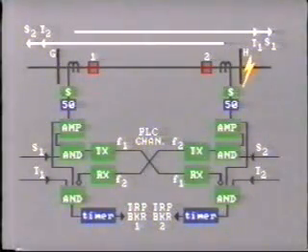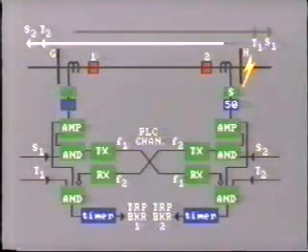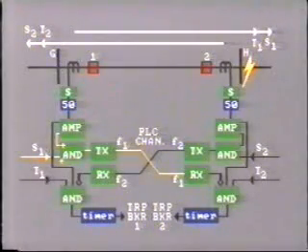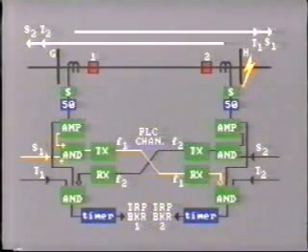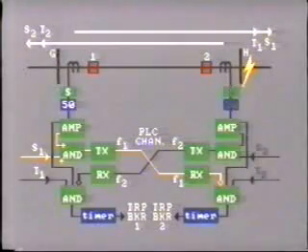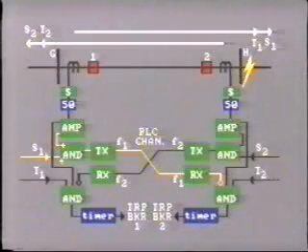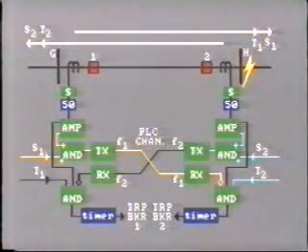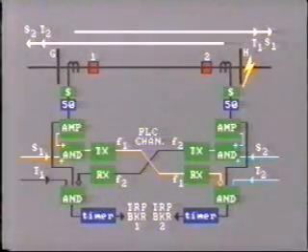close in. This fault is detected by both trip relays at station G. The starter relay starts the transmitter to send the half-cycle square wave signal along to the receiver and tripping logic at station H. The overcurrent relays at station H operate as non-directional. This starts the transmitter, and at the same time it sends a tripping signal into the logic circuit, attempting to trip breaker 2.